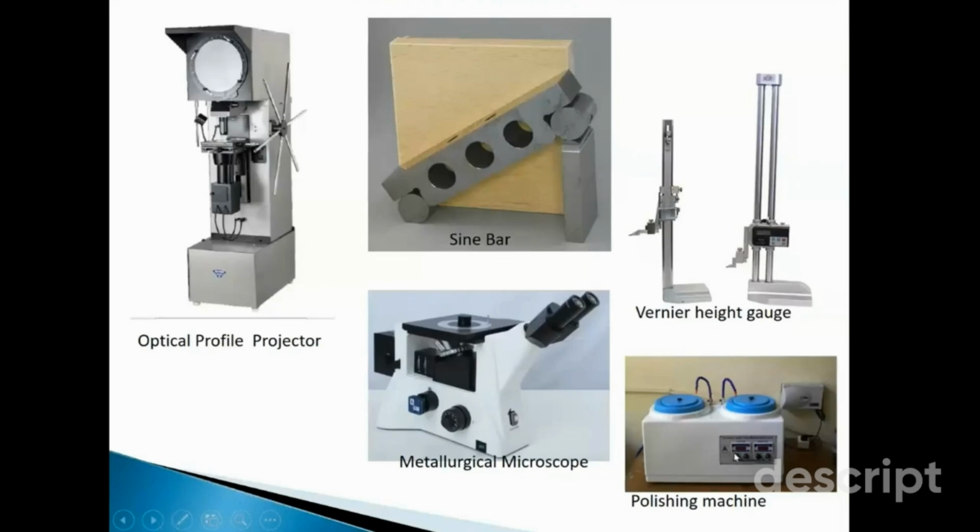We have a facility to fix the timer and to lock the RPM, and then you place your workpiece over this rotating table, and with the continuous abrasion and sliding motion of the rotating table, it smoothens and grinds the workpiece. After grinding and smoothing, polishing the workpiece, you place the workpiece on this particular table.